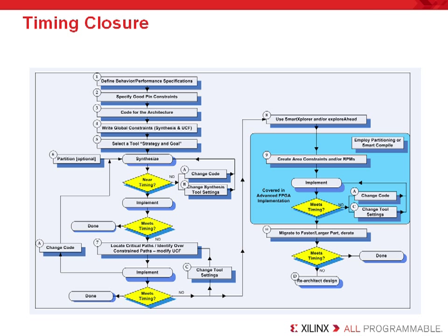Now, I'm not going to torment you by reviewing all the details of timing closure again. If you're wondering how all the details of the slides I just covered went into this, just replay this recording and note that I took you through this whole diagram and described all the possible solutions to gaining timing closure. Note that I did not describe the last option, which was buying a faster part. Trust me, if you get to this phase, it's not usually fun, but it does happen. And I will just say that we appreciate your business. The tools are not designed to recommend this option, but if you have an idea how fast your device can operate and good HDL experience, then you should not have to do this. In the end, most customers would say, I made this mistake while I was learning to do my first implementation.